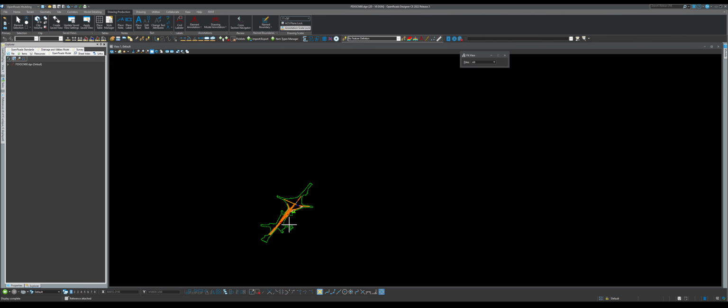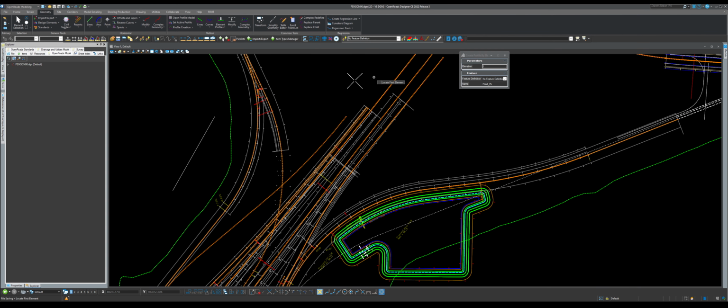So the first thing we need to do is activate the surface so we can create a 3D model. If y'all remember, in part 1 of the pond modeling, I said we can do this. We can just draw any line and then go to the element and give it a constant elevation. It can be just one, it doesn't matter. So click on it, and then reset, and then click again. And then here we go. It created a 3D model for us too. Here we go.